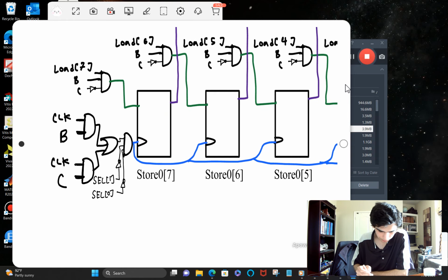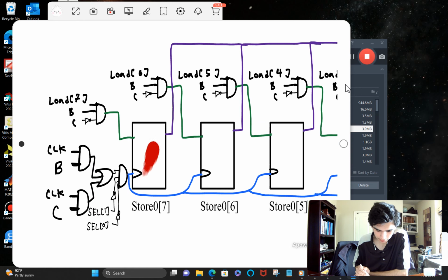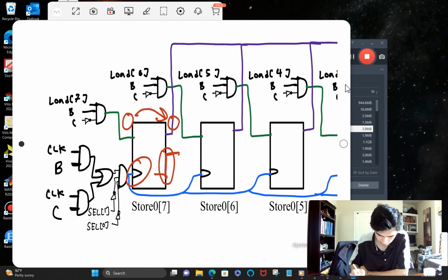And let me explain this right here. How the flip-flop works is whatever value is in here is going to instantly move over here. So if this is a 1 and this is a 0, this should change to a 0. So yeah, this moves there. But the thing is, that only happens when there's a clock pulse. If there's a pulse in that very instant, whatever's here is going to move here.